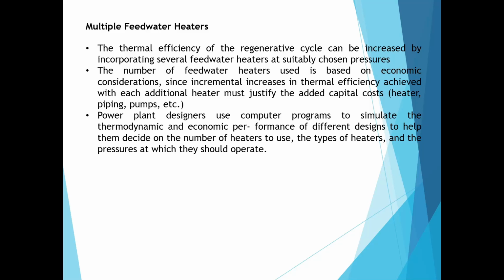Adding a feed water heater is initially a high cost, because you need heat exchangers, pipelines and everything, and that increase in capital should be justified by the thermal efficiency gain from adding that feed water heater, right?